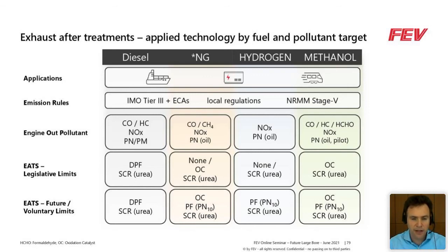post Stage 5. And the different combustion systems will trigger different engine pollutants compared to what we know today. Today we know very well NOx, NPN, and particulate matter as emissions of a diesel engine. When we go towards, for example, hydrogen or methanol, NOx will still remain an issue for hydrogen, even though we have said before that we can realize very, very low engine-out emissions of NOx also with hydrogen. And with methanol, for example, we will also have HC emissions and formaldehyde emissions.